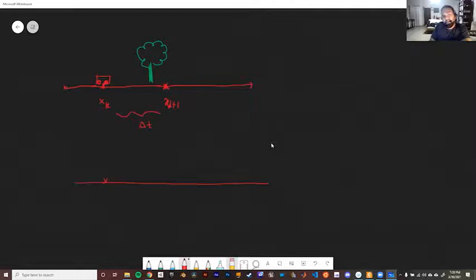So let's go through the Kalman filter algorithm now, right? Imagine this robot is first moving forward to this xk plus 1 location, and we had some sort of control signal u. I'm going to make this very simple. I'm going to make the motion model the simplest possible motion model that you can consider. I'm just going to assume that xk plus 1 is simply going to be equal to xk plus uk. Right? So what are the quantities that we have? We have xk and we have uk.